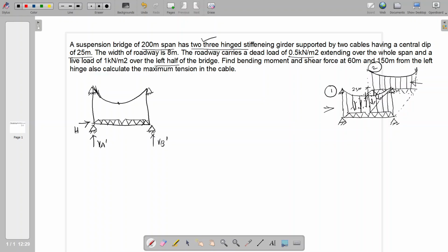I am indicating it as H1 at the girder level, and the suspenders are specified like this. If the problem is given as an area load, you have to convert into equivalent UDL for our calculation. Otherwise, the problem is very normal.